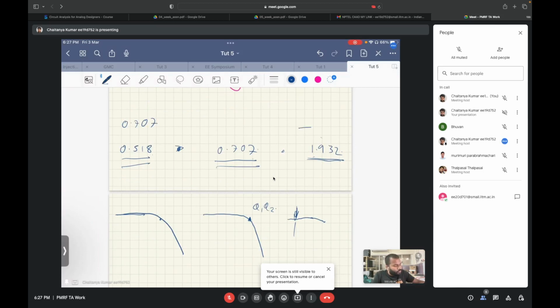In this, what will happen is the magnitude response of this biquad will look something like this. Okay, individually, I'm not talking about the cascade. Individually, it will look something like this, and you will think that since this peak is going above one, I should attenuate it a little bit. But in practice, when you cascade all these biquads, due to the attenuation at omega naught from previous biquads, its peak would have already reduced. So you would not need to attenuate this. You will not need to scale the last biquad to the extent that you were doing initially.